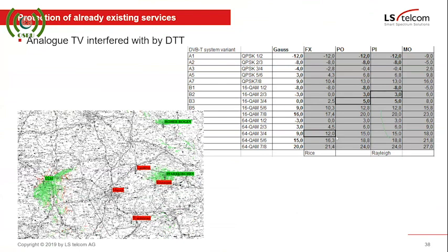Okay, so you will see that in any sort of network deployment or conversion from analog to digital, you will always be confronted with existing transmitters and new transmitters. In very few cases will it work that the two are not on air at the same time. So when you introduce your DVB-T2 network, you will still be sitting with analog services. So you might have a plan where you will first keep certain stations on air on the existing frequency.